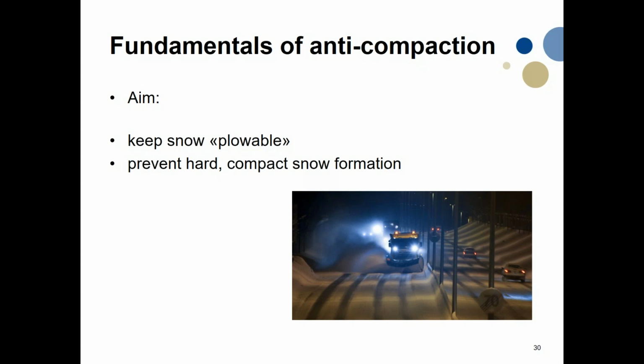So the real aim of adding chemicals prior to a snowstorm or during a snowstorm is to keep the snow plowable. It is not to melt all the snow. If you do that, you will need much more salt or chemical than you typically would use. I think that's the biggest misconception in winter maintenance, at least by the general public, that the purpose of the chemical application is to melt all the snow away. It's mainly to prevent the snow from getting compacted and forming a very hard compacted layer, which then gradually turns into ice. So I like this word, keeping the snow plowable.